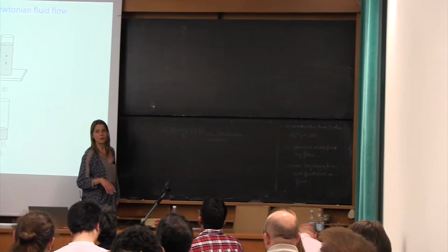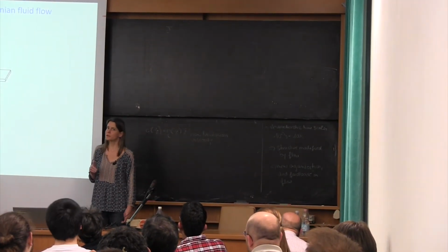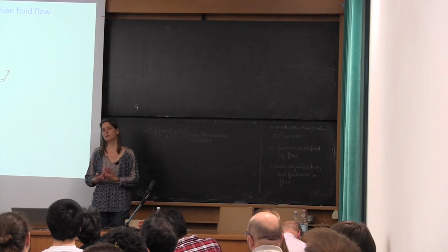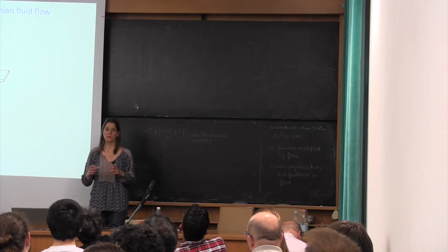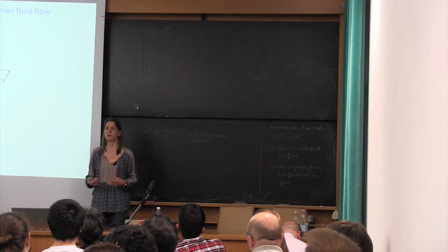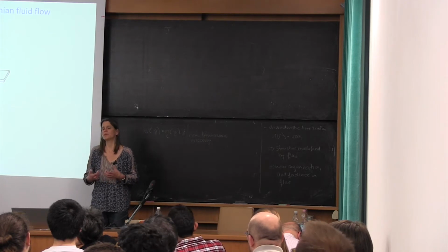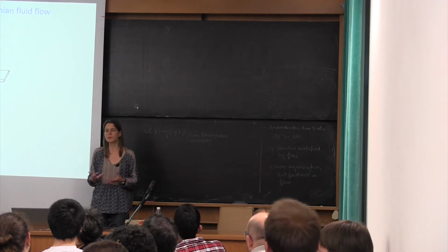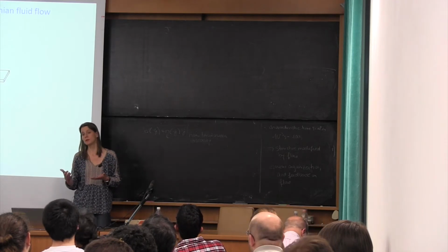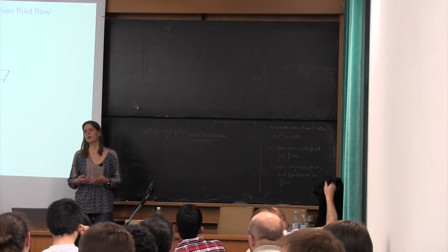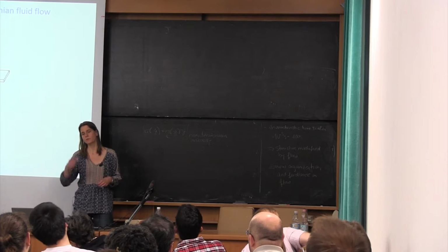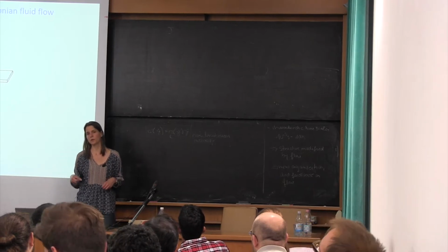And something that I should also say that I didn't clearly state is, so we've seen that for all non-Newtonian fluids, there's an internal time scale. So it's very important to know about these internal time scales, and actually non-Newtonian effects will only occur if your shear flow is strong enough to overcome the inverse of the internal time scale.